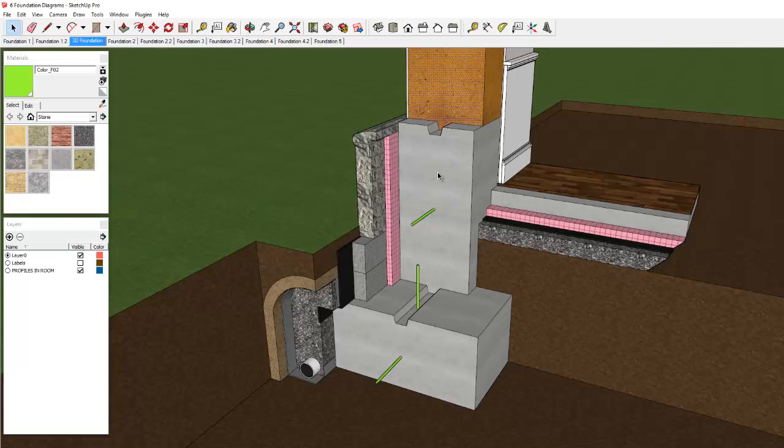It can take moisture, but a lot of moisture is bad for it and can get in there and cause a lot of damage over time. So we want to keep our cob wall well up above the ground. Usually a foot, foot and a half above ground is good, unless you're in a very arid region, like if you're in the southwest, like Arizona or somewhere.